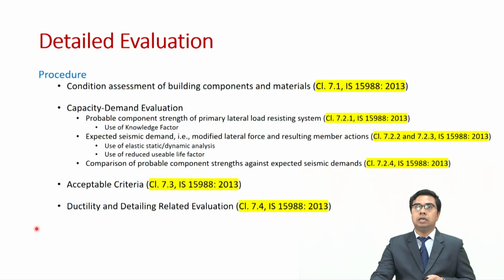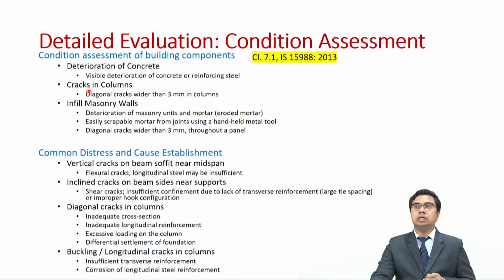So, the first thing, let us look into the condition assessment of building components and materials. When it comes to condition assessment of building components, we shall look for various distress signs in the building. It can be in form of deterioration of concrete or cracks in various structural members or infill masonry walls.